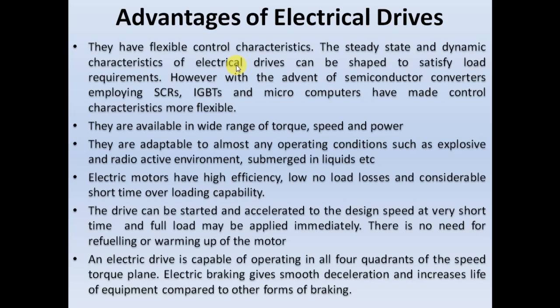That is, based on the load requirement, we can vary the operating point in the torque slip characteristics of an induction motor. That is possible either by varying its supply voltage or supply frequency, or both. This change in supply voltage or frequency or both can be achieved with the help of semiconductor converters.